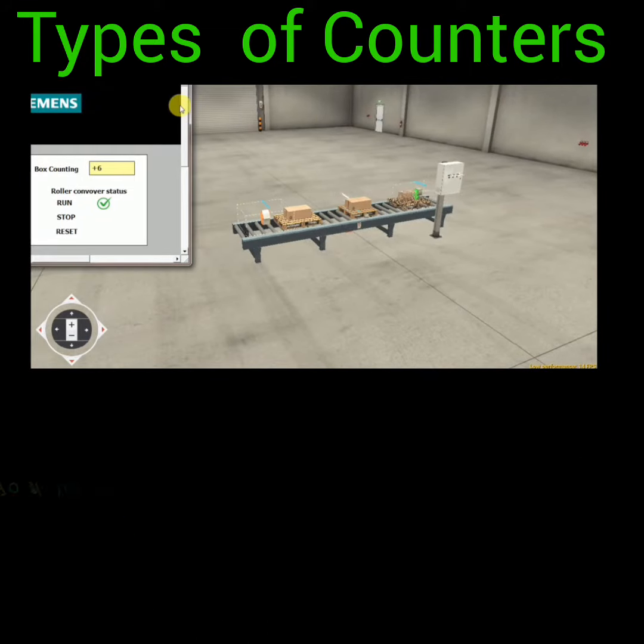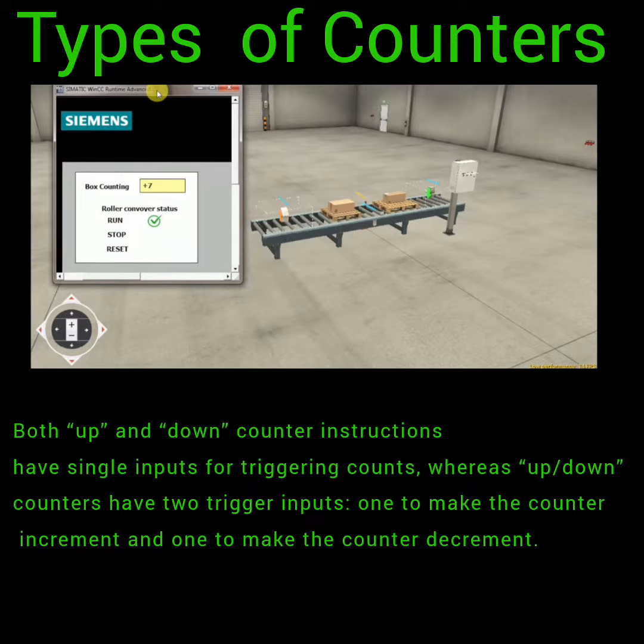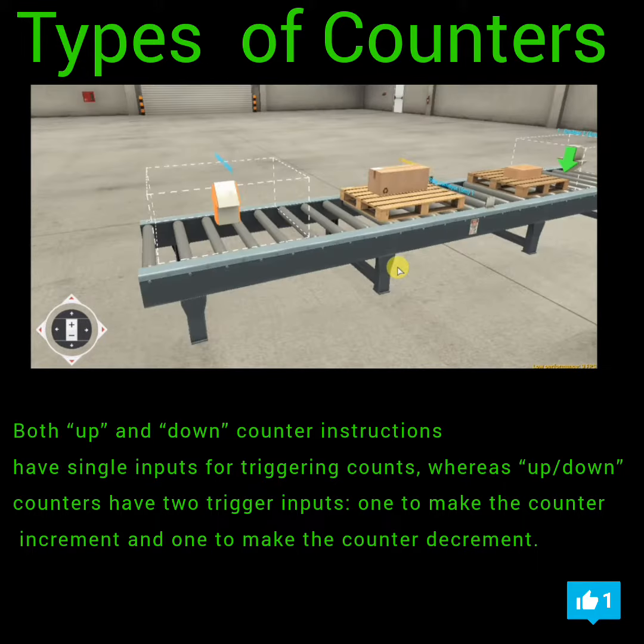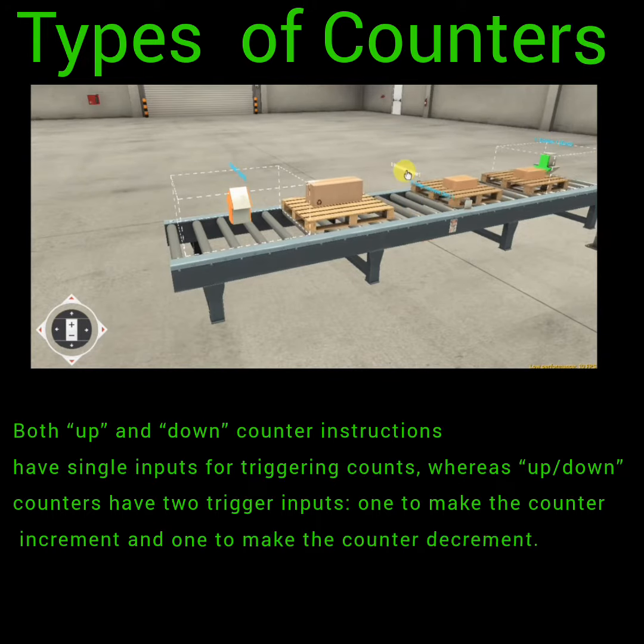Both up and down counter instructions have single inputs for triggering counts, whereas up/down counters have two trigger inputs, one to make the counter increment and one to make the counter decrement.